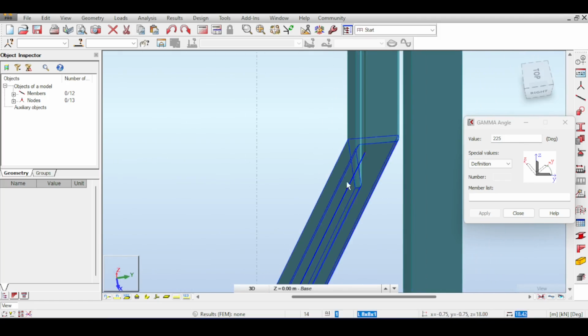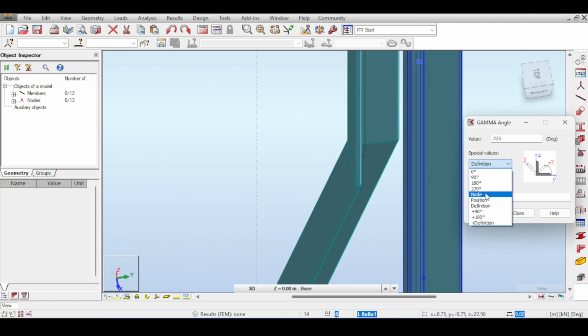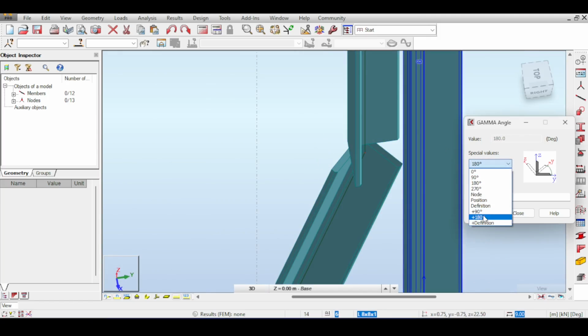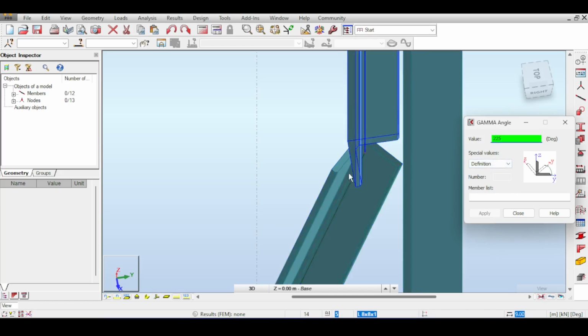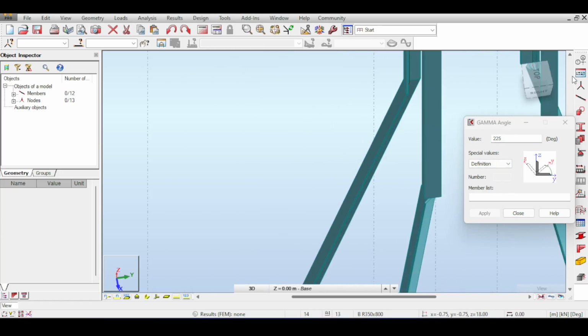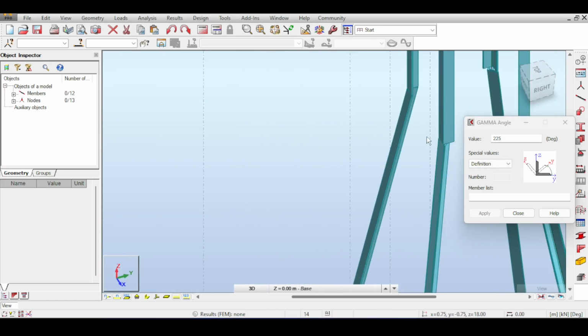So it's possible to put a plate here, basically, or a gusset plate or whatever. When I did 180 before, it was this. It's very hard to plate it. And this is an extremely important thing, not only for this project, but in engineering in general. You should always keep in mind what the practical considerations are. Don't just blindly put sections.